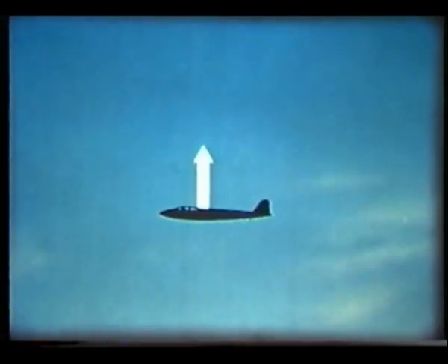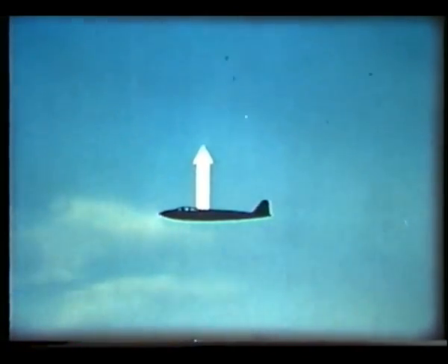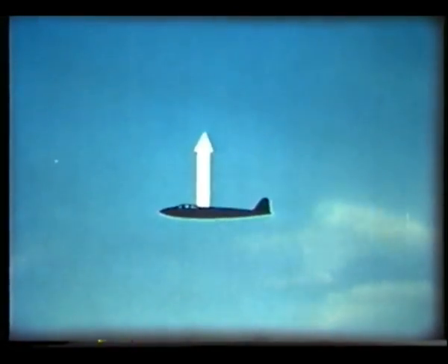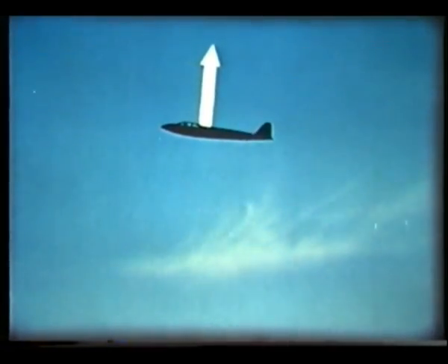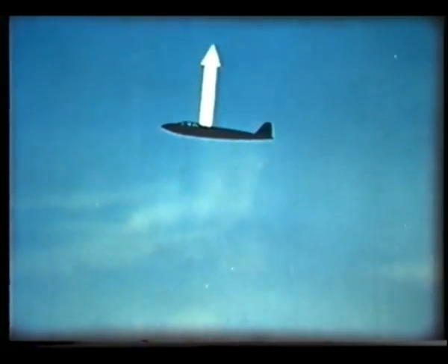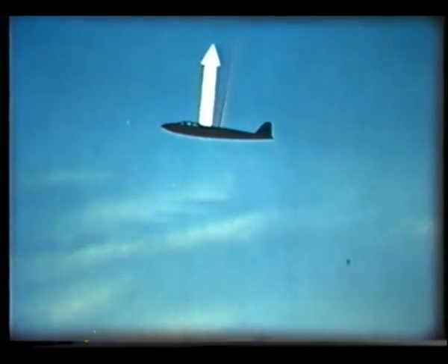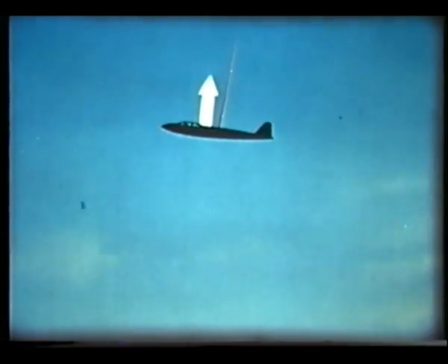The shock stall can also cause instability. For instance, changes in fore and aft trim. First, lift increases slightly just below the shock stall. This causes the aircraft to gain height, assuming the pilot takes no correcting action. Next, at the shock stall, the sudden loss of lift puts it nose down.